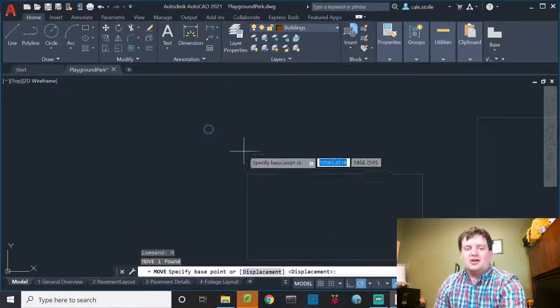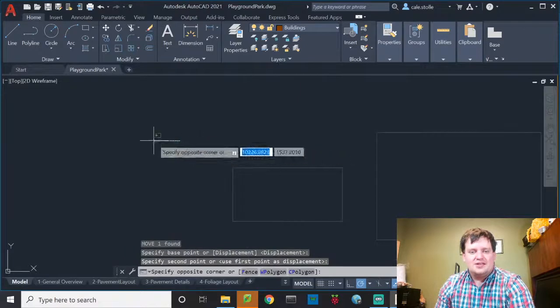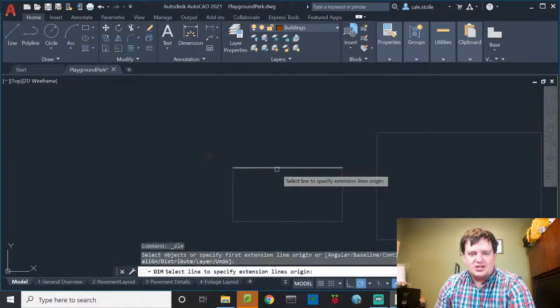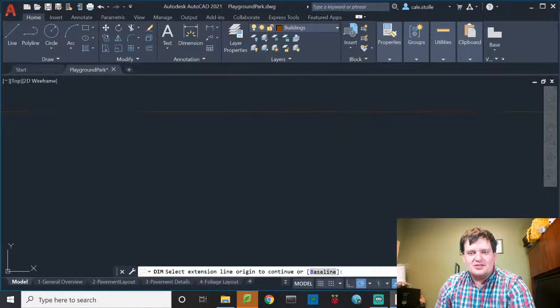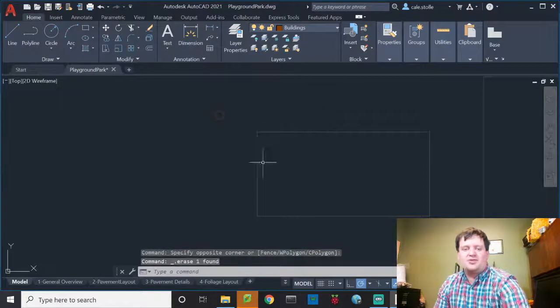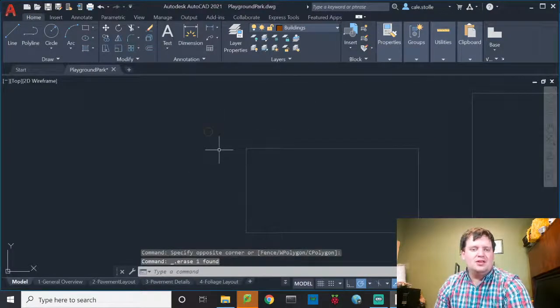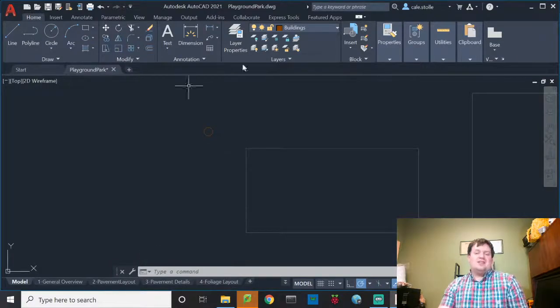I'm going to move that into place. And this right here, if I just take a quick dimension of this, zoom in, it's 40 feet. Okay, so this is 40 feet, but I believe that's 20 feet. So I'll probably want my pylons to go out about 5 feet by 5 feet more. So I'm going to be looking at designing a 50 by 30 real footprint for my building.